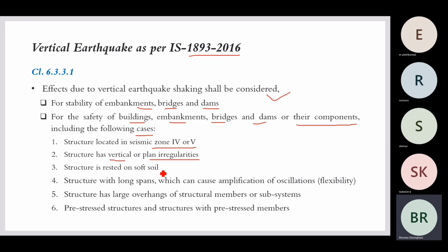That is compulsory. When the structure is resting on soft soil, it is obvious that with the earthquake it will start moving, and the above ground structure will experience a vertical effect, and that's why we should consider vertical earthquake where there is soft soil.